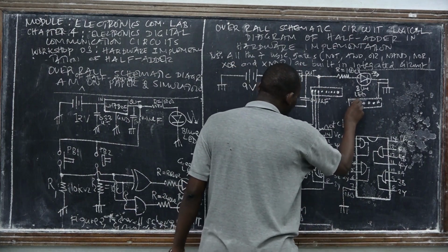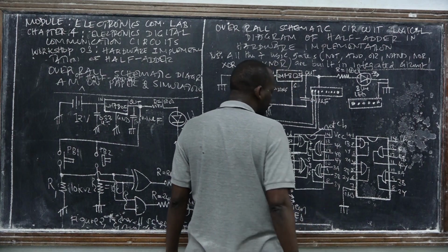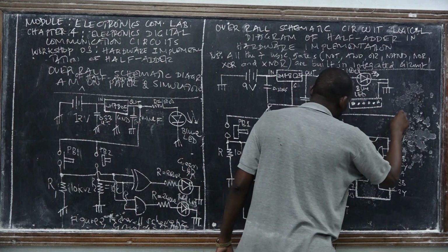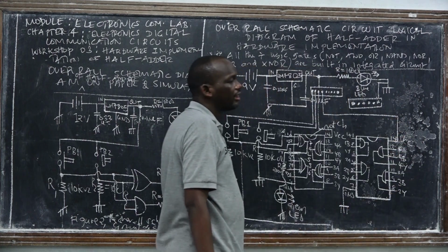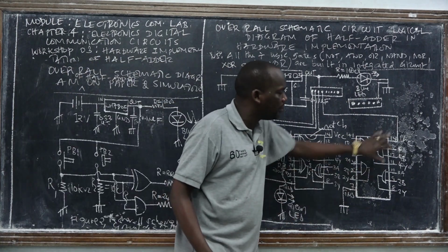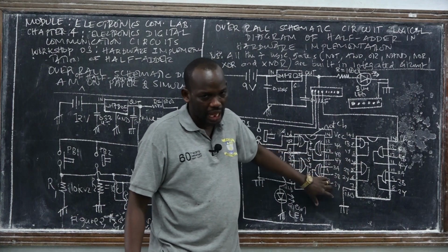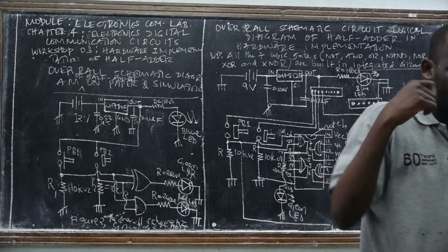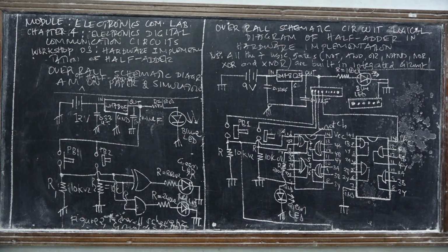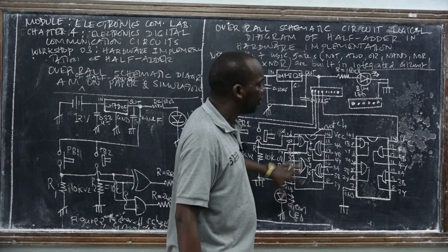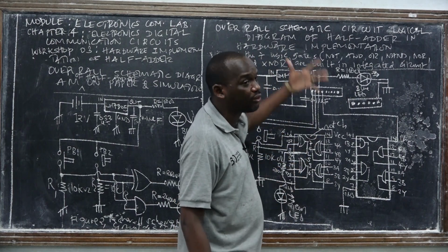So I mean that, for instance, you can take a jumper and connect with this one. So we have connected the common ground. We have connected the power supply for the AND gate. So when you connect the power between pin number 14 and pin number 7, all the logic gates built in the integrated circuit have power. So these are the common pins for four logic gates, or 6 logic gates, or 3 logic gates, or even 1 logic gate.